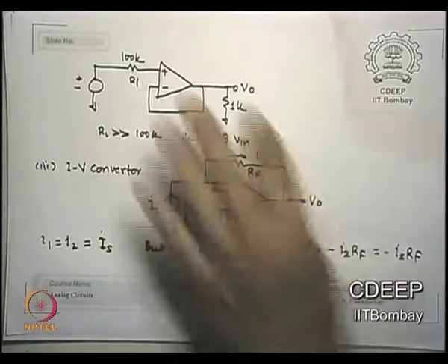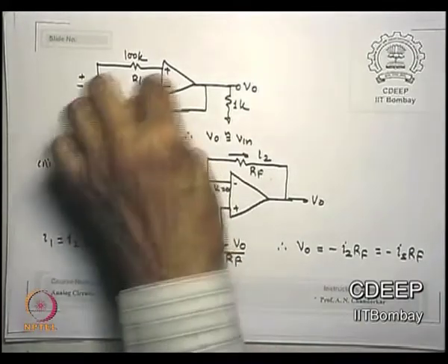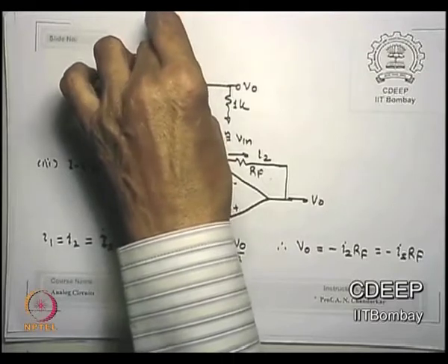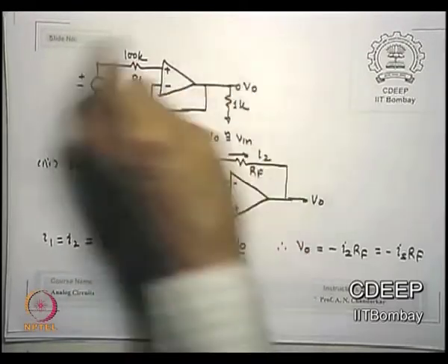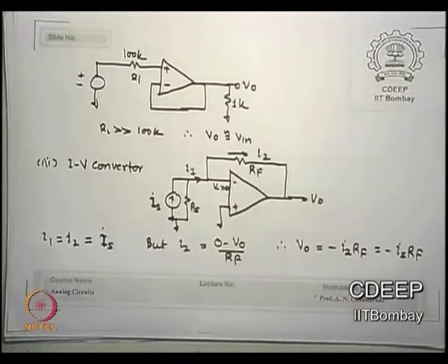Is that clear? Here the 1k does not affect the 100k side circuit now, because this has a very large resistance, allowing all of it to appear here, and as a follower, all of it will come out. So now you get full Vin across it. Now if you wish you can further boost it by R2 by R1 if you need. The first stage must be a voltage follower. Is that okay? Thank you for the day.